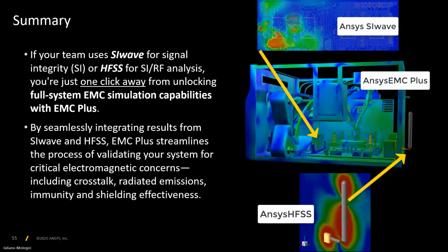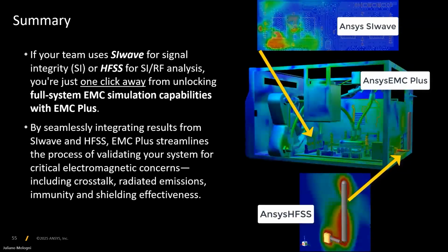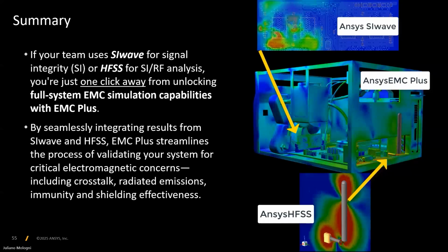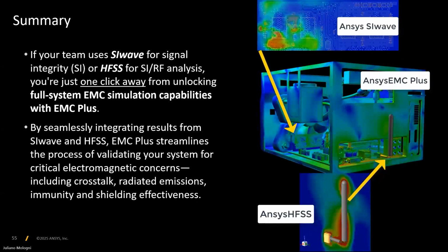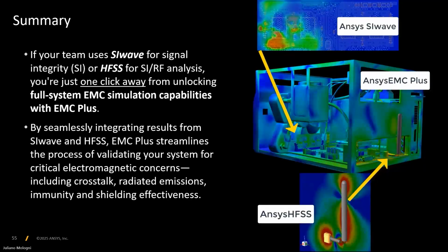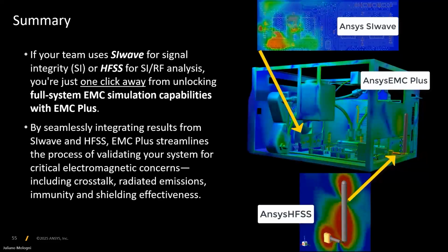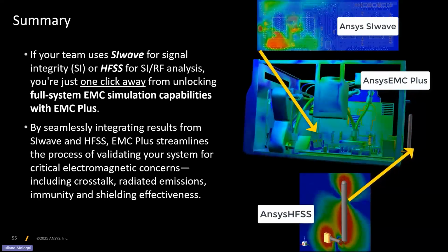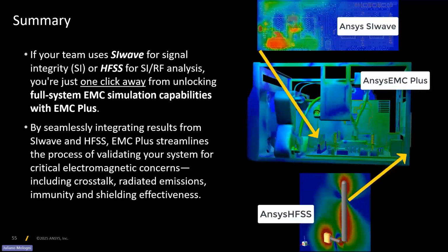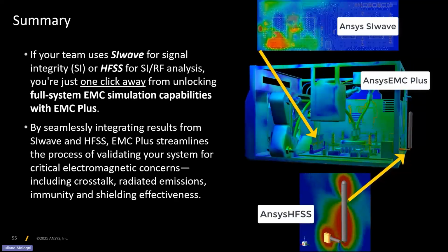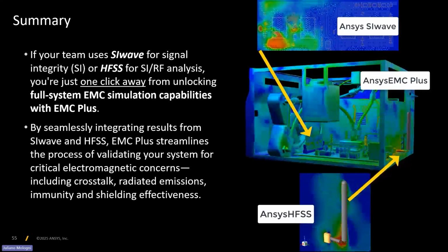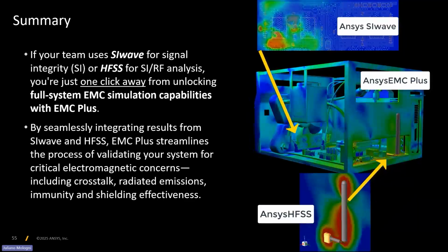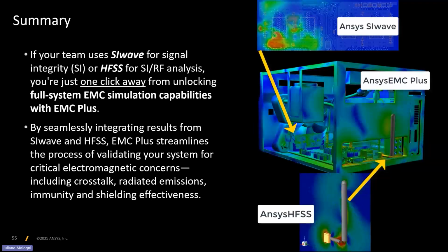Excellent. Thank you. Next question is, for encrypted HFSS components, the field coupling to and from the encrypted geometry with the rest of the setup is bidirectional, not unidirectional like a Huygens box? With the 3D components, there's no field link. The actual geometry is there, but only the solver can see it. So there's no field coupling like what we're showing here with the Huygens box. The Huygens box here is one way, right?